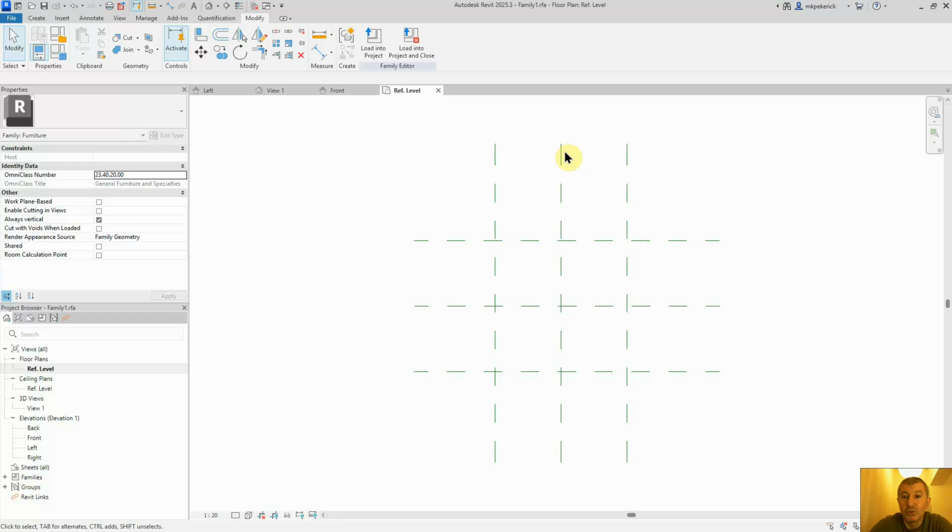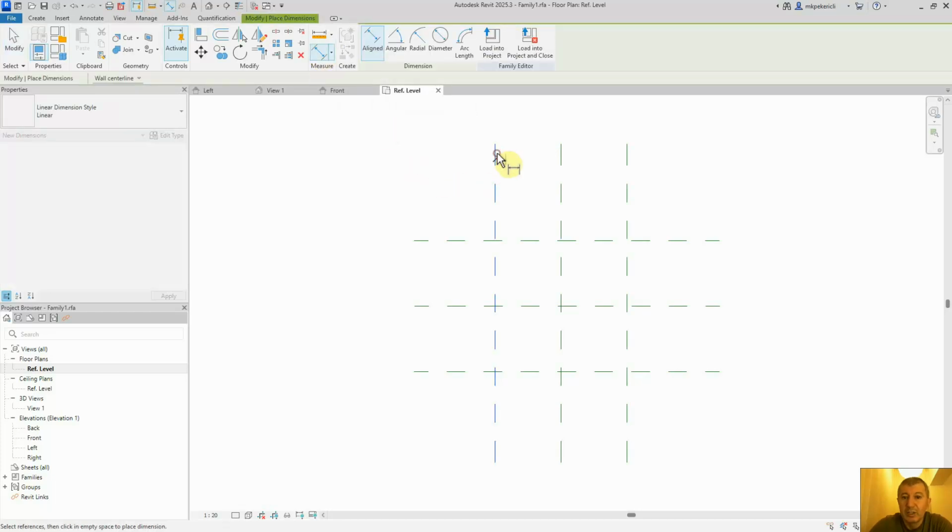So I need to use the measurement command, create a constraint between these, let's say, reference planes for equality. So when I create the measurement, the equality constraint is off. If I click on it, it is now on, equal, okay? Good. So I want that first. Second, I create a measurement between two ends, 1200.